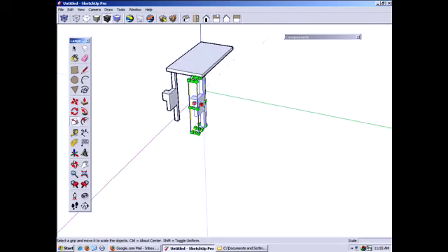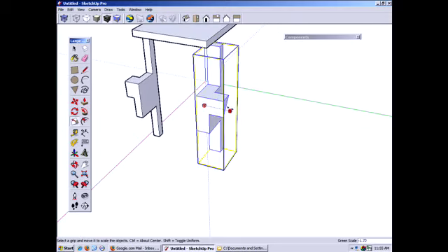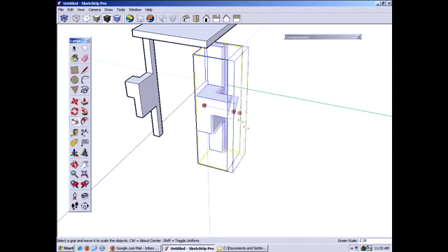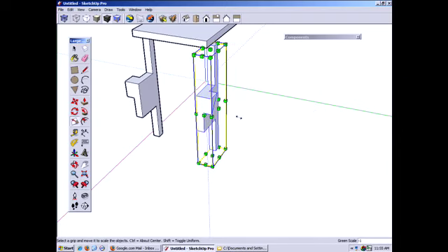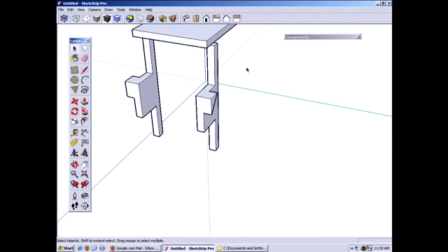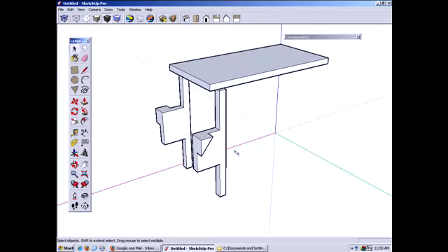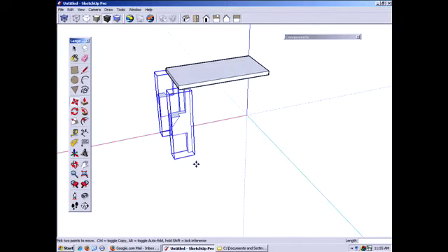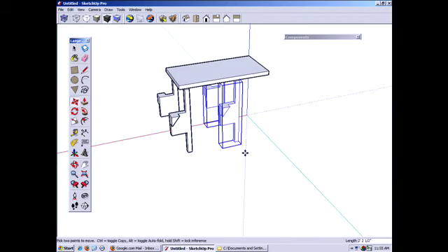So I'm going to undo that. In this case, I want to mirror it about this direction. So I'm going to take it back. It will also snap at -1. For those of you who can see, down in the corner here, it'll say -1, or just type in -1. So I have a mirror. Now here's something. Oh wait, let me do this again. Now I'm going to select both of these, copy them, and mirror them.